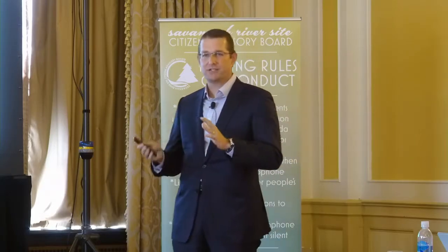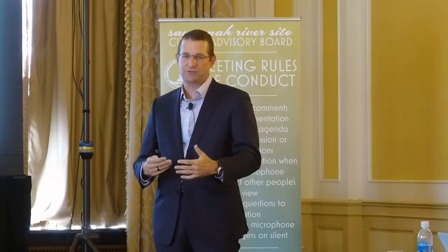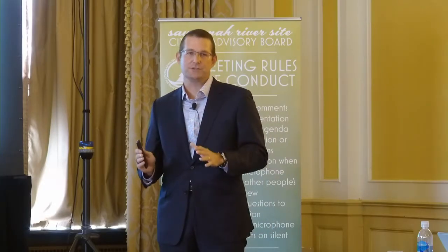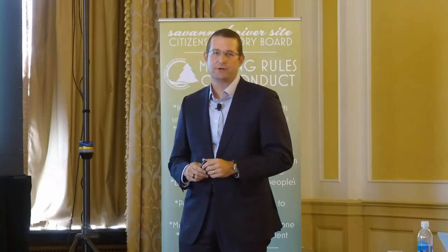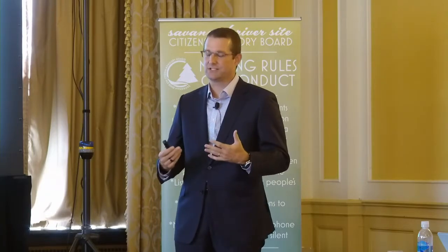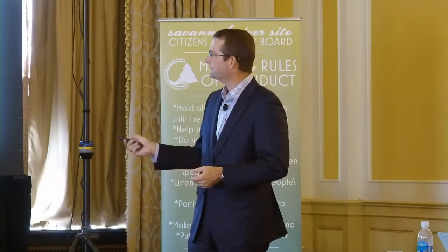Because premix that is accumulated in the feed bin is fed continuously, again through a weigh hopper, and then through 2 screw feeders. And these screw feeders are what provide the process control function. They determine the rate at which we are going to be consuming dry material. Nominally, we talk about everything in terms of the dry feed rate quoted in tons per hour. And a nominal feed rate for us would be 30 to 35 tons of dry material per hour. It is a very high instantaneous rate process. That's a lot of material to be moving.